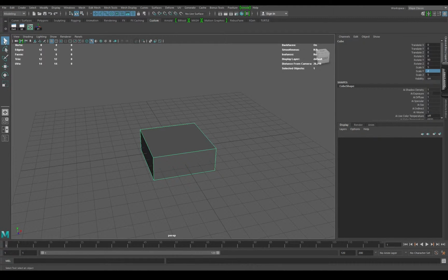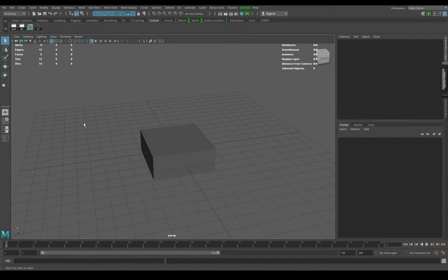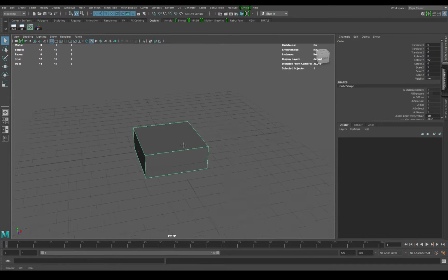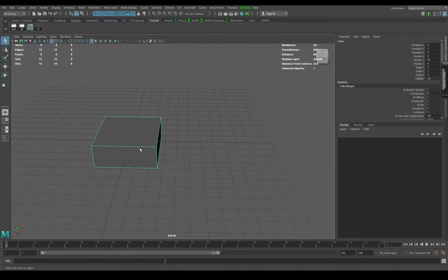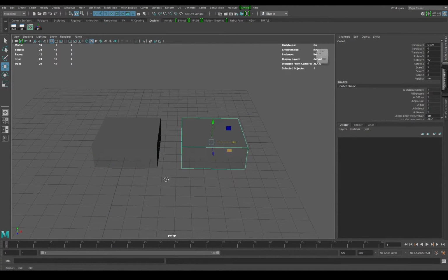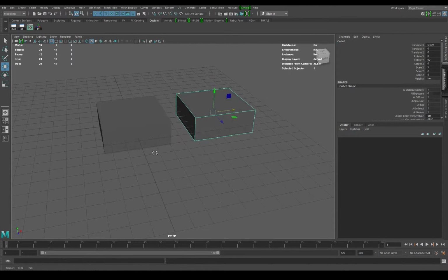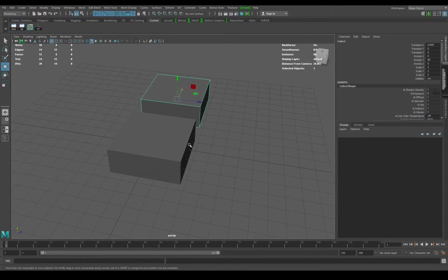We've covered this. This is a select tool. If I just click anywhere on white space where there's nothing, it deselects everything. If I click on my object, I get my object. If I duplicate, Control D, now I've duplicated the object and I want to move it, click on my move tool and I've got 2. We'll come back to duplicate, don't worry, but I'm just showing you. So Control D duplicates and I can move it.